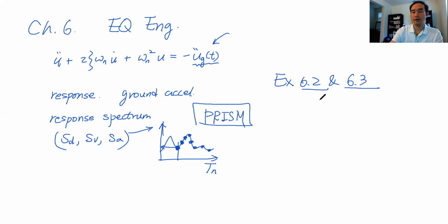Then we find the maximum peak deformation, and we should also be able to find the maximum bending stress using this equation, MC over I. This bending moment comes from the equivalent force times the height of the structural system, and C is the maximum value of Y, with I the moment of inertia. So we should be able to find the maximum bending stress.